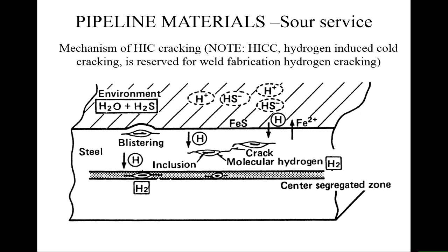But in the case of material where we're handling CO2 and hydrogen sulfide, in particular in hydrogen sulfide, there are clear corrosion reactions which will create hydrogen, and that hydrogen can diffuse into the material. So it's a very likely explanation, and it's fairly well proven.